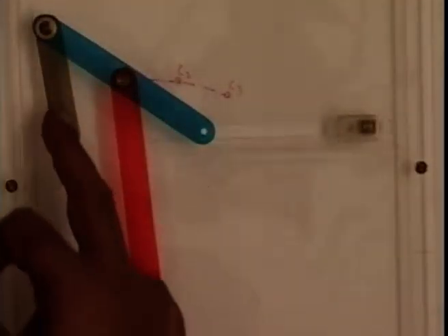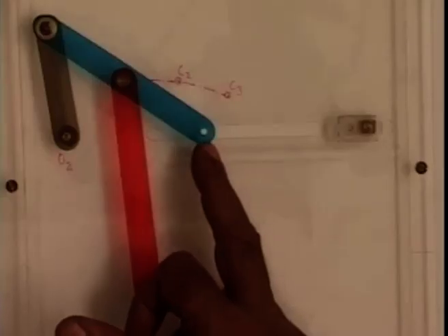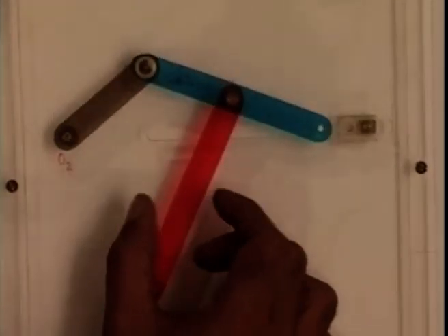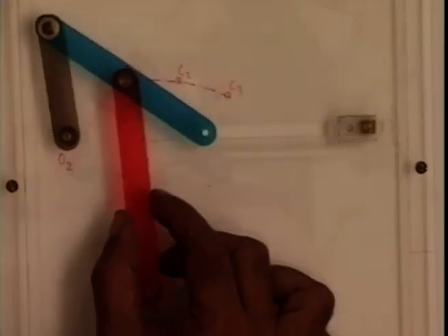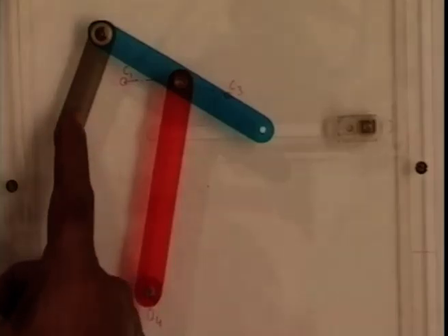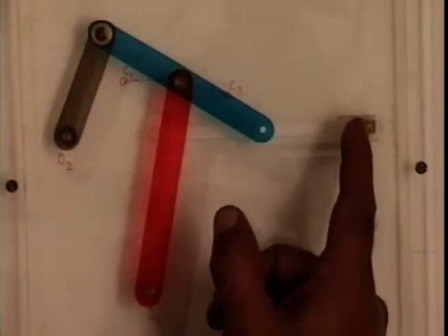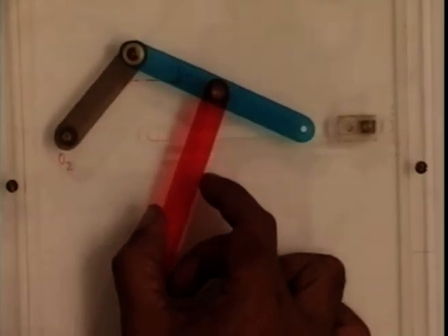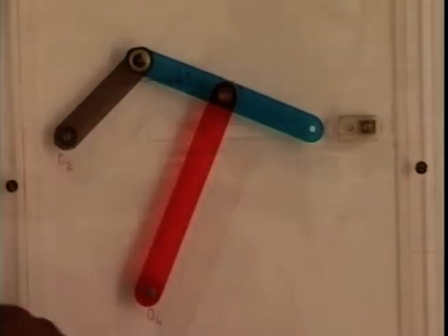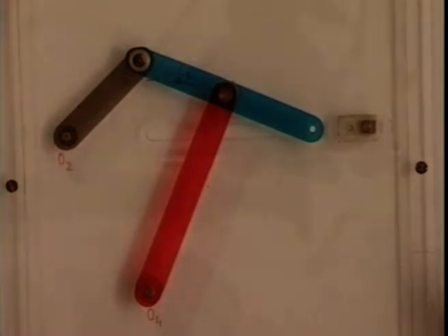So we get a 4R linkage with this coupler point generating an approximate straight line as we have seen earlier. And as it goes from position 1 to position 2, the movement of the crank is exactly same as it had with the slider crank. Similarly, the movement of the crank from C2 to C3 is again theta 2, 3, which is coordinated.